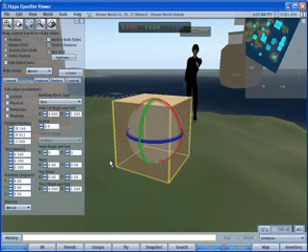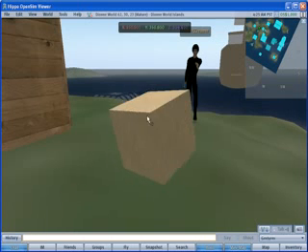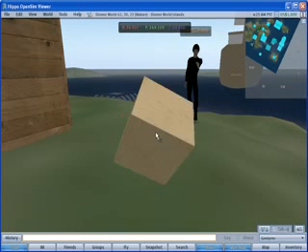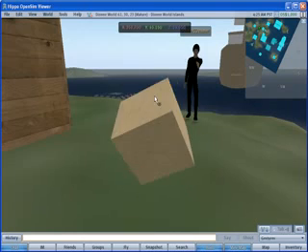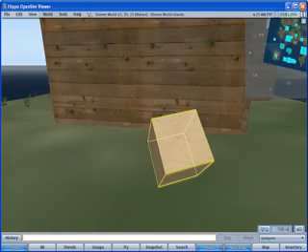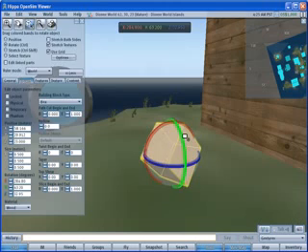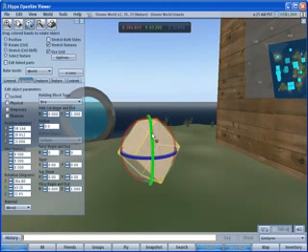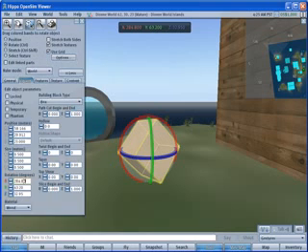Okay, enough of that silliness. So you can click on these bands, or if you click in the middle, you will enter free rotate, which is a little confusing, but can allow you to create just about any random rotation for no reason. But we don't like it like this, do we? Maybe some of you do, but I don't. So the easiest way to get an object back to 0 rotation is to go here and zero out the rotation: 0, 0, 0.